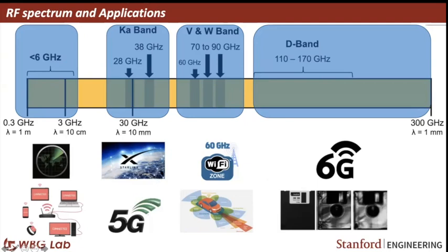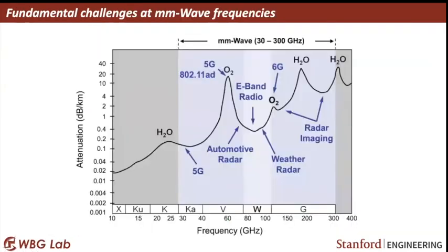And one thing I was also thinking about initially, right? Why are they dividing into such bands? Why are some frequencies in these regions not used? Why are there some gaps? This is something I was also thinking initially. The reason for that is interesting. It basically falls on how the atmosphere attenuates different frequencies. That's what is shown here.